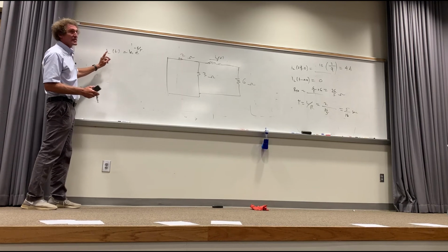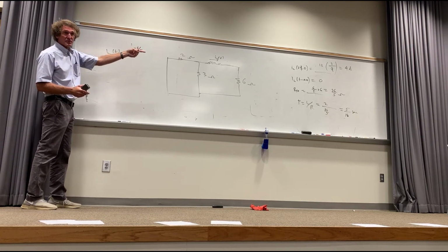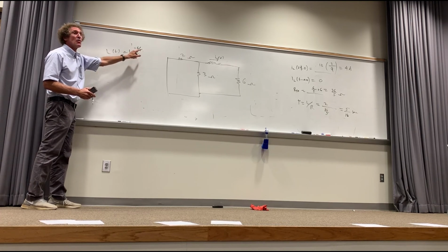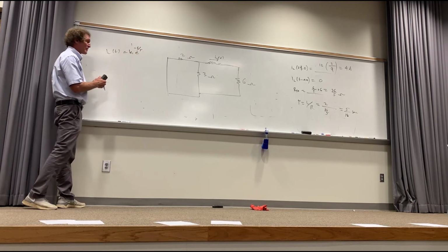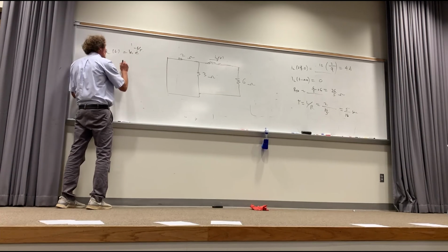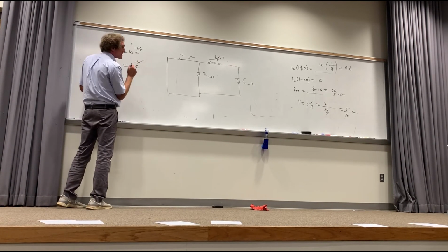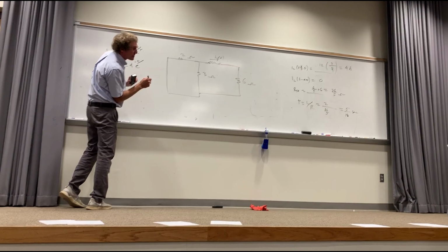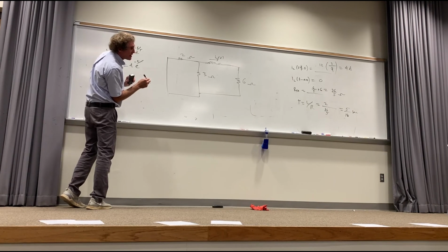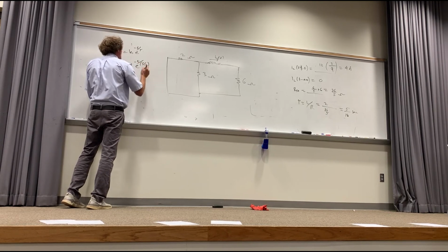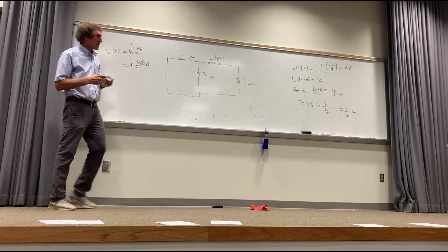What is the current at t equals 0? 4 amps, right? 4 amps equals K1 e to the 0, so K1 is 4 amps. You agree with me? That's 4 amps. So the current is 4 e to the minus t, and I know the time constant is going to be equal to 5/18 of a second. That's it. That's the current through the inductor.